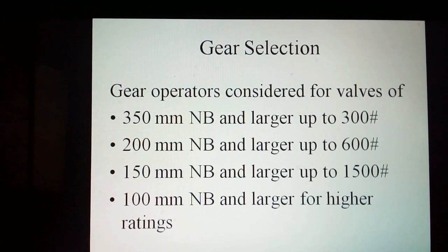As a guide, gear operators should be considered for valves of 350 mm ND and larger up to 300 psi, 200 mm ND and larger up to 600 psi, 150 mm ND and larger up to 1500 psi, and 100 mm ND and larger for higher ratings.